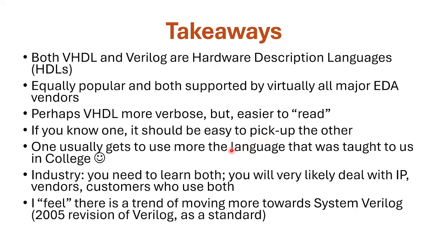In my experience, the best way to do that is start with an example in Verilog or in VHDL and port it, translate that functionality into the other one, and in this way go through the experience of seeing and understanding all the concepts from one world and another.